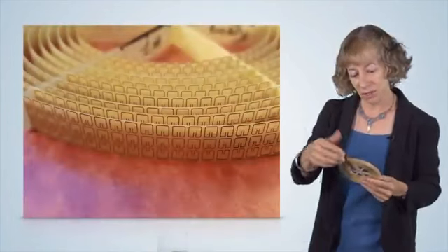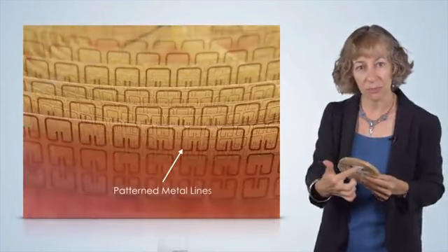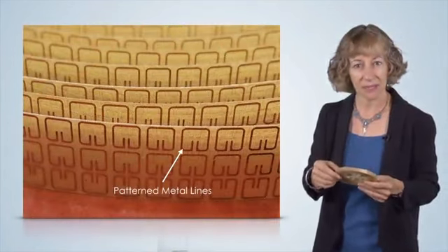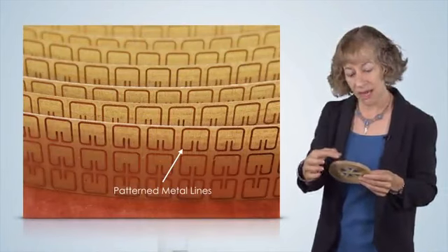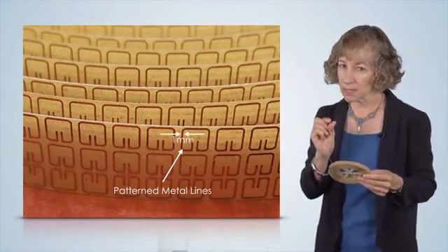The next example I'd like to show you is called a metamaterial. The metamaterial that I show you here is the first ever reported invisibility cloak, and this was made by the David Smith group at Duke University. This metamaterial is patterned metal on dielectric printed circuit boards that have been bent. You can see that the metal pattern has lines that are about 1 millimeter wide. This metamaterial bends electromagnetic waves around a metal object that we put in the center of the ring.